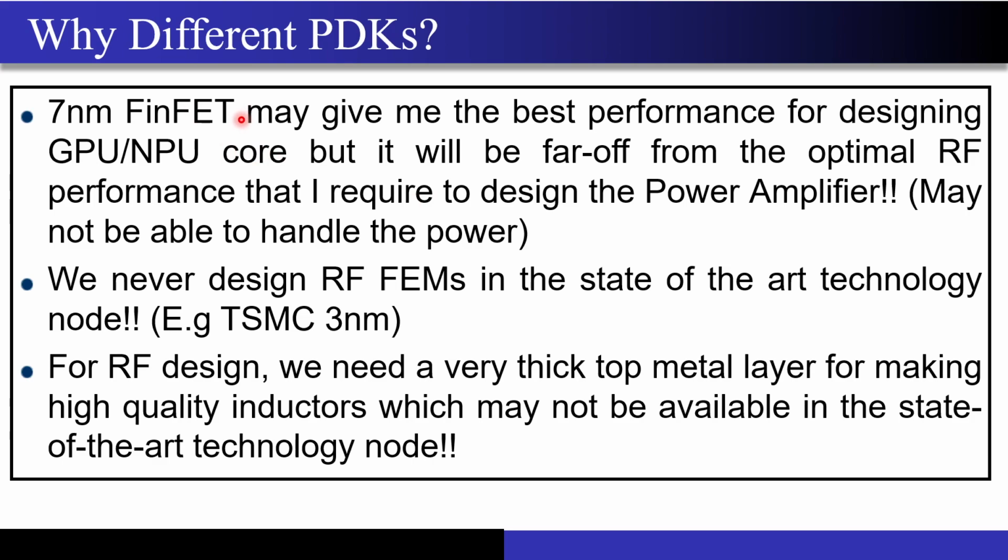This is the same thing that I have highlighted here. A 7 nanometer FinFET may give you the best performance for designing GPUs or neural processing units that are required to train your neural networks and for inference, correct? When you are using that kind of application. But if you try to design your analog or RF circuits here, you are just going to mess up.